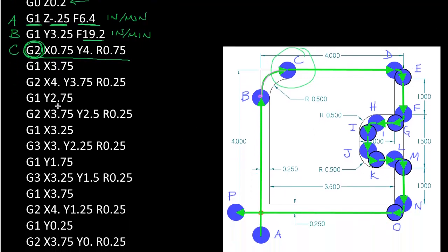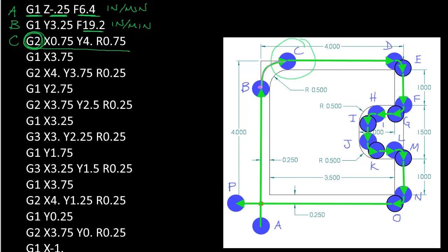All right, so let's go line by line. We're going to do a linear interpolation motion to point D. So this is point D. Then we're going to go to point E. So this is point E right here, and we're not using a linear interpolation motion. We're using a circular interpolation motion in the clockwise direction, which is G02 or G2. Okay, so this is point E.